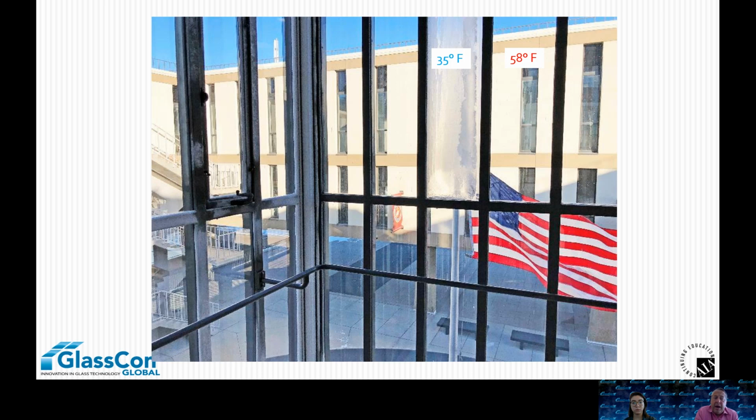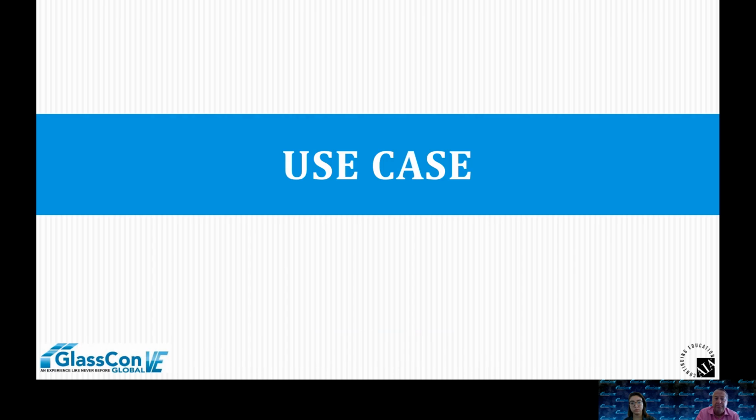So you look at what the impact was. This is one of the windows that they had, and I think this one got broke by sticking a ladder through it, or something like that with the project. But we had to reglaze it with just monolithic plate glass until the replacement can show up. And you can see on this cold winter day, it's 35 degrees on the inside, a ton of condensation and frosting, and then that's what leads to that corrosion and that cycle of maintenance. The VIG right next to it doesn't frost up. The inside temperature of that glass is about 58 degrees. Your view's better. So really, it's a really nice fit in these sort of scenarios.